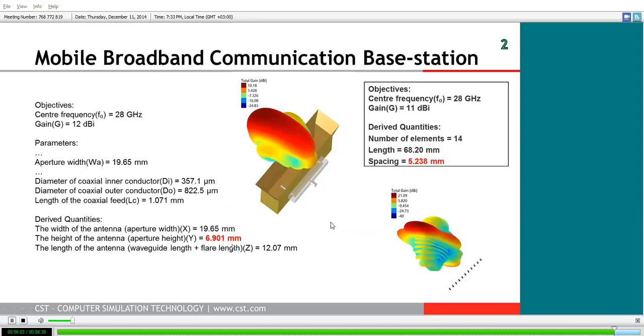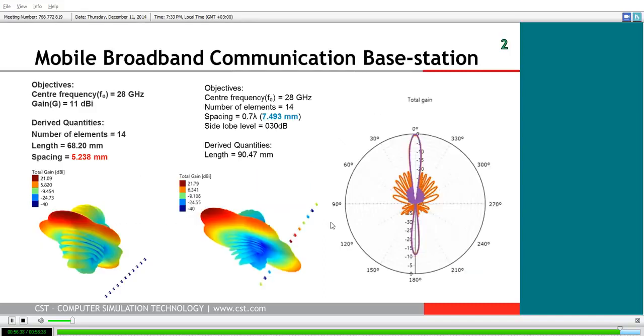And you can see here, if we arrange these in a hexagonal layout, we get a reasonable sectoral coverage with nice gain. If we compare this to what we obtain with our waveguide antenna-based array, we create at first our individual element, and in particular of note here we see that the waveguide height of our element is just shy of about 7 millimeters. When we try and build an array to increase our target gain, what we find though is that Magus suggests a spacing between elements that is smaller than the physical height of the waveguide, which is obviously not realizable.